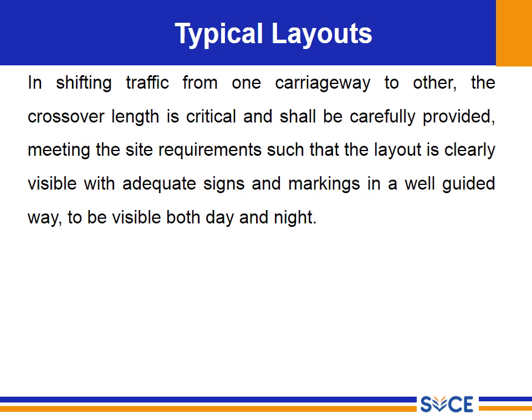In shifting traffic from one carriageway to the other, the crossover length is critical and shall be carefully provided, meeting the site requirements such that the layout is clearly visible, with adequate signs and markings in a well guided way, and visible both day and night. So this should be done very carefully.